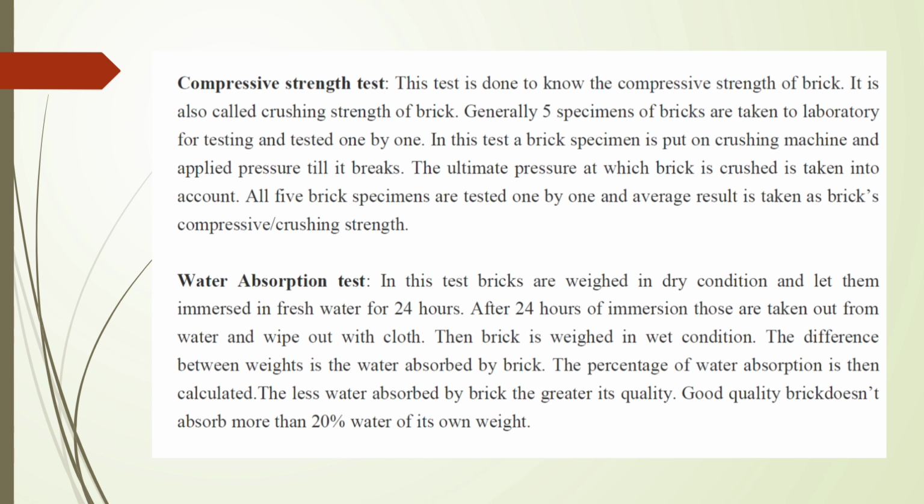In this test, a brick specimen is put on crushing machine and applied pressure till it breaks. The ultimate pressure at which brick is crushed is taken into account. All 5 brick specimens are tested one by one and average result is taken as brick's compressive or crushing strength.